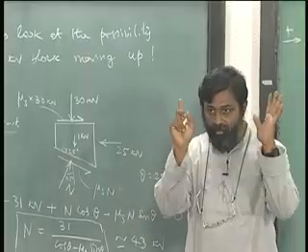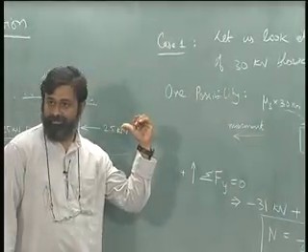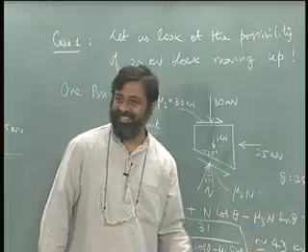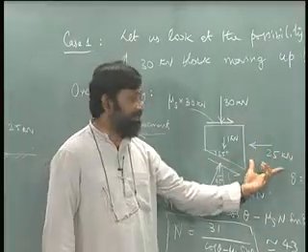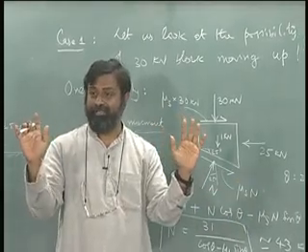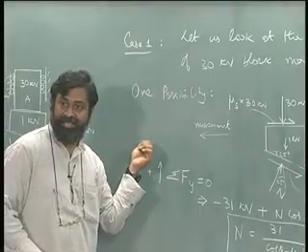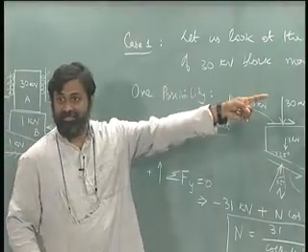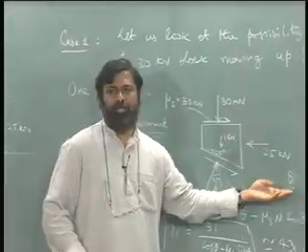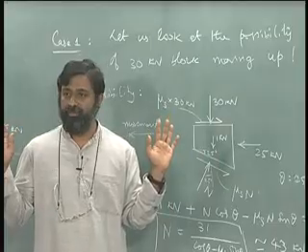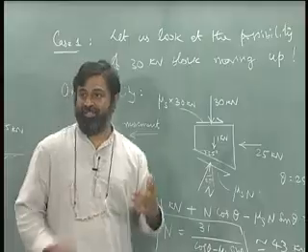So two things that I have found out now, the movement is not to the left, the movement is not to the right, because I have already shown that 25 kilonewton is more than enough to keep it in place, and if 25 kilonewton has to push it to the left hand side, the possibility does not exist, we have seen that. So left hand side movement is not possible, right hand side 25 kilonewton is more than enough for it to keep it in place, which means it is in the static condition as far as this block is concerned.